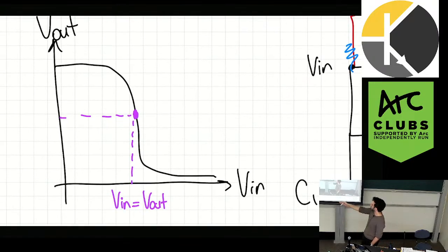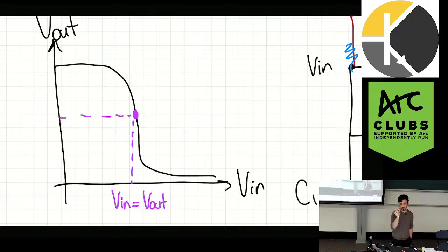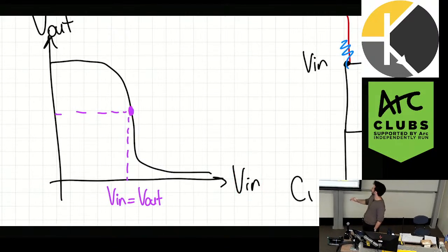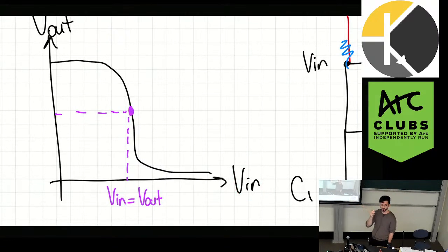So you can imagine, I've turned it on, I'm sitting at this middle point, and then there's a bit of noise. Where does it flick? Left or right? It's probably right because we're adding noise, but you can see how steep it is, right? It only requires the most minuscule of pushes at the input to go to the right and to go to this point here. So I'm sitting here. This is my input. This is where it's biased by default. Then I get a bit of an input, and it pushes it this way. And if I push even a bit this way, I fall, like that. Does that make sense so far?